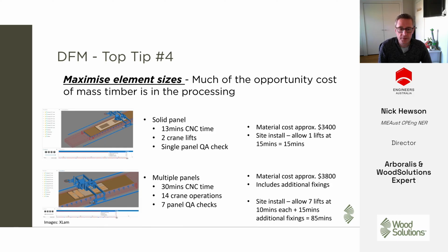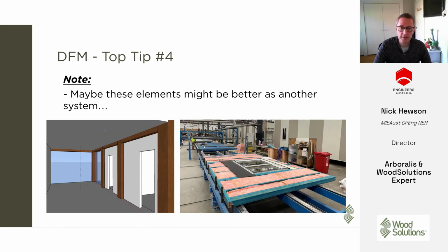It's not to say that this is going to suit every project. Certainly, there are some projects where it would potentially be more cost effective to do the other one, where you're limited by craneage or access or something. But in general, trying to maximize the size of the pieces we can get to site is going to result in something cheaper.